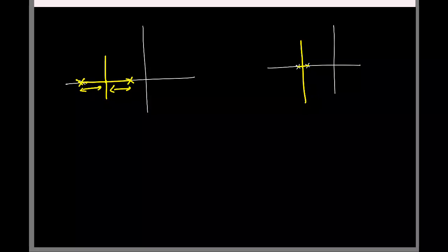We also came up with one other technique. Remember that? Feed forward, and the idea was basically you introduce a 0 here, so that the root locus kind of does this, right? So this is another way in which you can keep the closed loop poles on the real axis. You introduce a left half plane 0, and that is called feed forward.